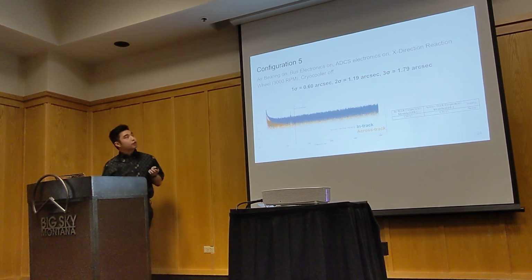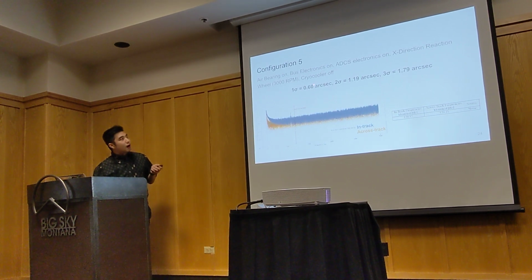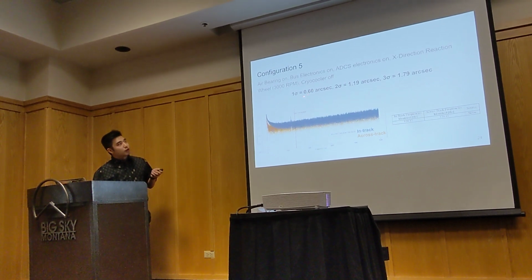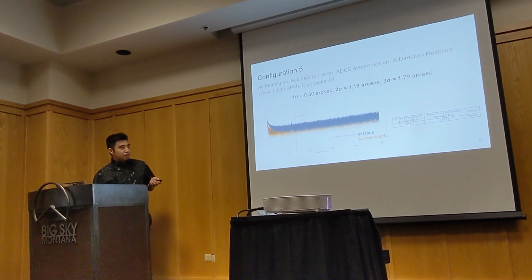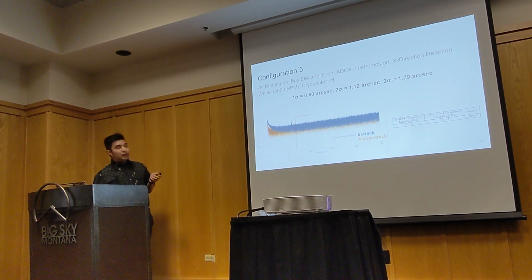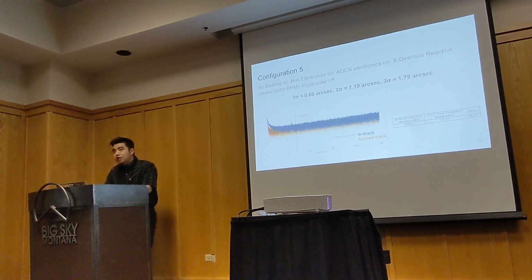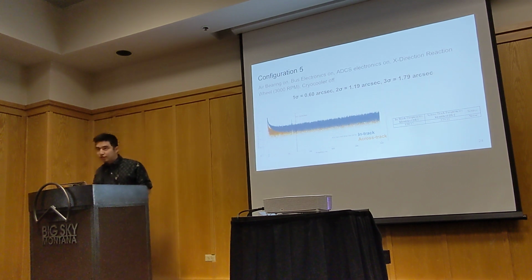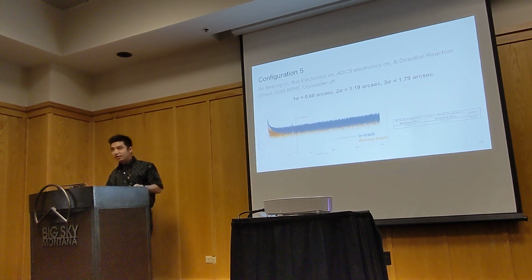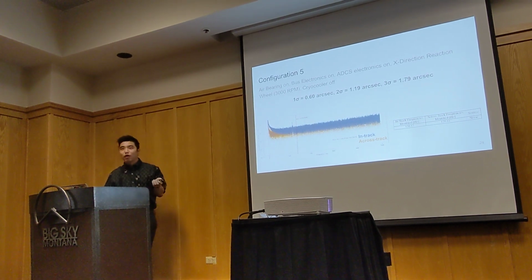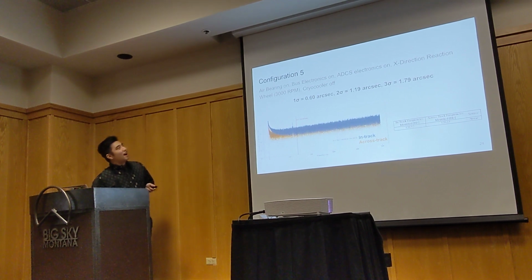Now we turn on the X direction reaction wheels at 3,000 RPM. We see a significant drop in the RMS pointing value below 1 arc second, but we still see that same noise mode. And interestingly, we don't see a peak where we might expect one, which is about 50 hertz. This actually makes sense given the dynamics of the system. And again, in the interest of time, I would love to go over it if anyone has questions about that.